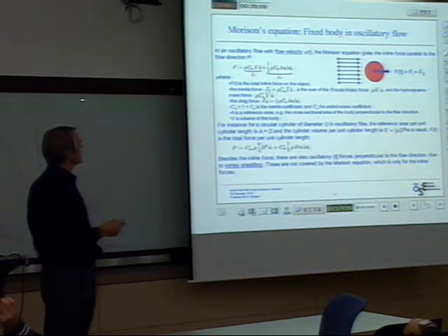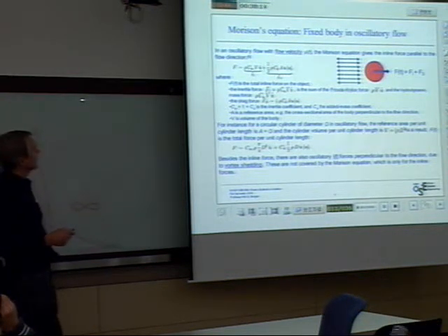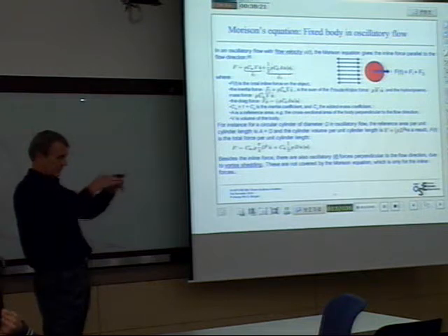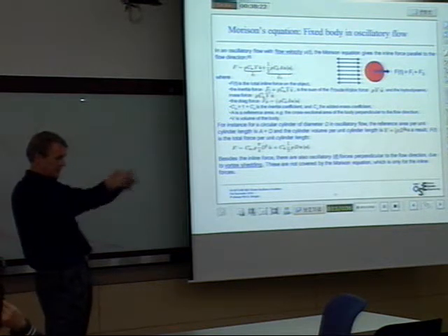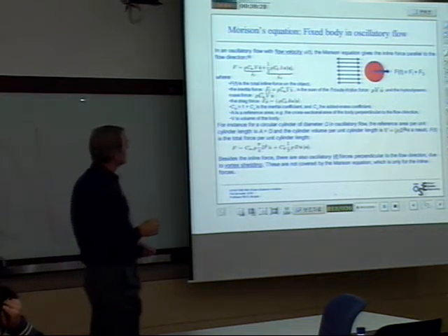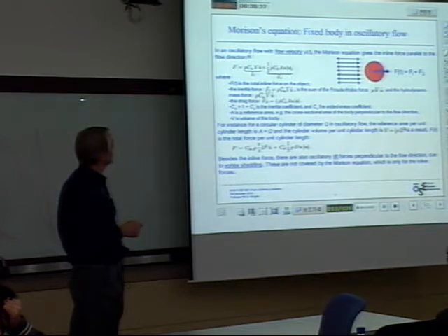and here you can see the kinetic energy. But again, there's a coefficient here that depends on the geometry of the body. And then you have the area. If you have a flow in that direction, then the area is the outline of the body. But this coefficient depends on whether this is, let's say, a sphere, or a plate, or whatever. You have different drag coefficients. And here you see the velocity times